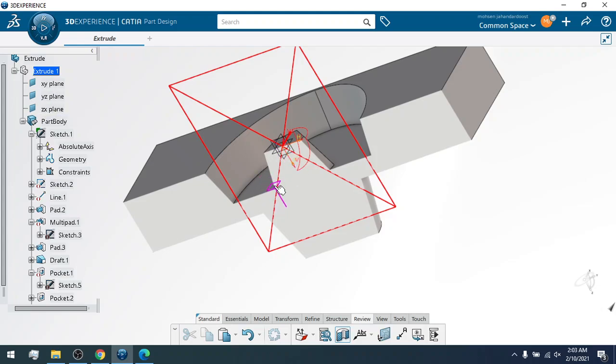So here you can see that this is my end of my cut. I had the profile in the top, and then I have 15 degree outward here. So the second circle is bigger than the profile that I created, and also the second cut or the second draft is inward. So the dimension of this hexagonal in the top is smaller than the one that I created.